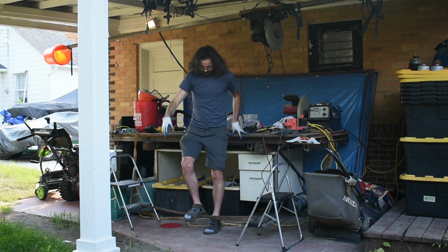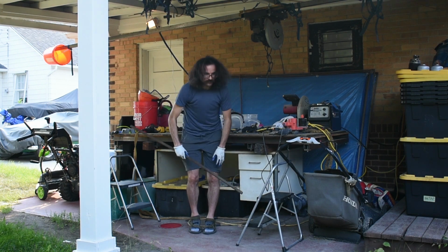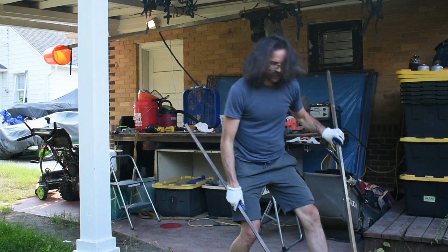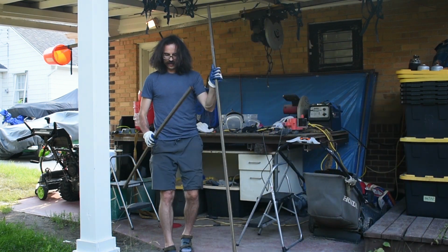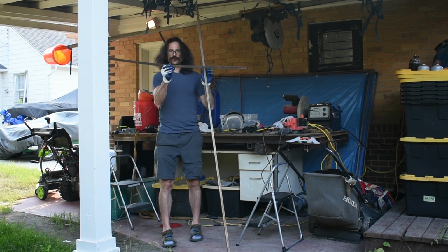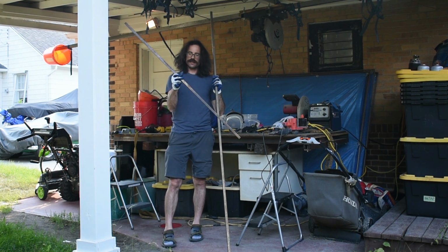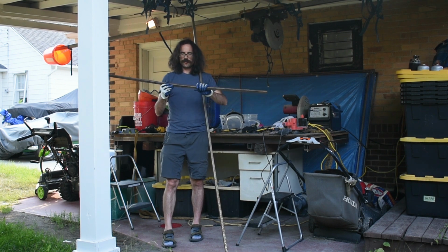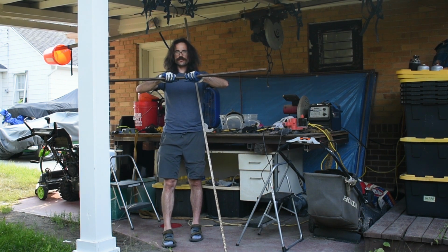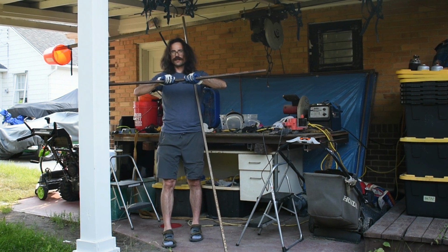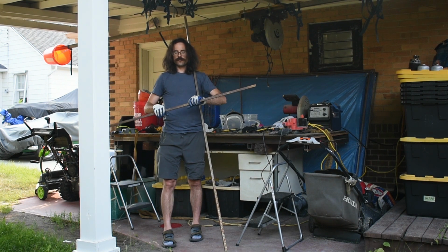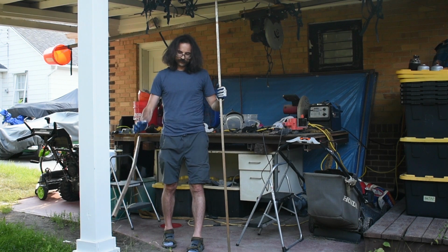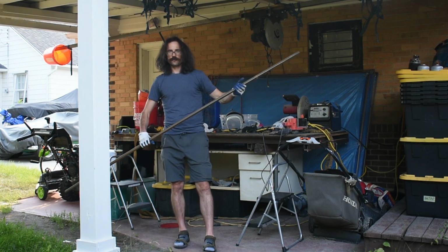But yeah, this thing's permanently bent. What I did is I brought a longer piece just to see how much you could go, but no. So this held, but it is bent. So it passed the modulus. It passed the yield stress. So some part of this got more stressed, and then has a permanent change in length. So it definitely wasn't linearly elastic for that one.